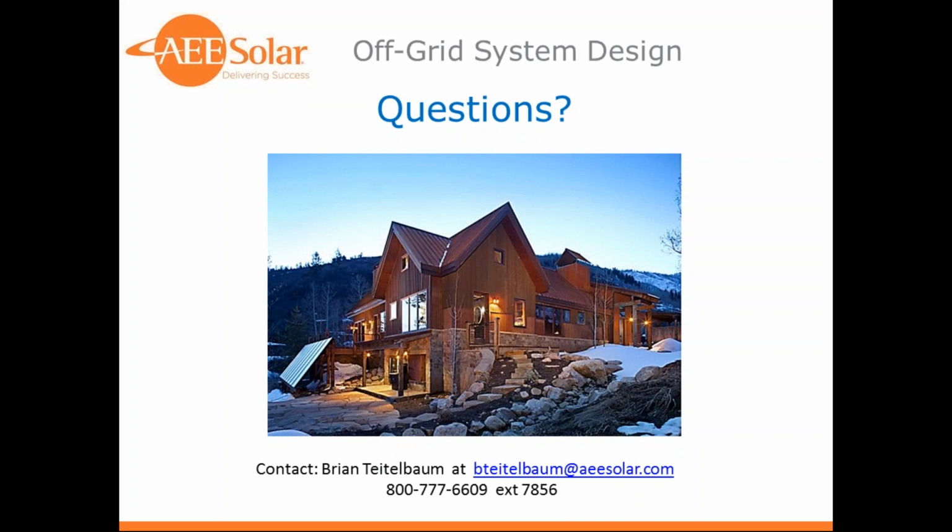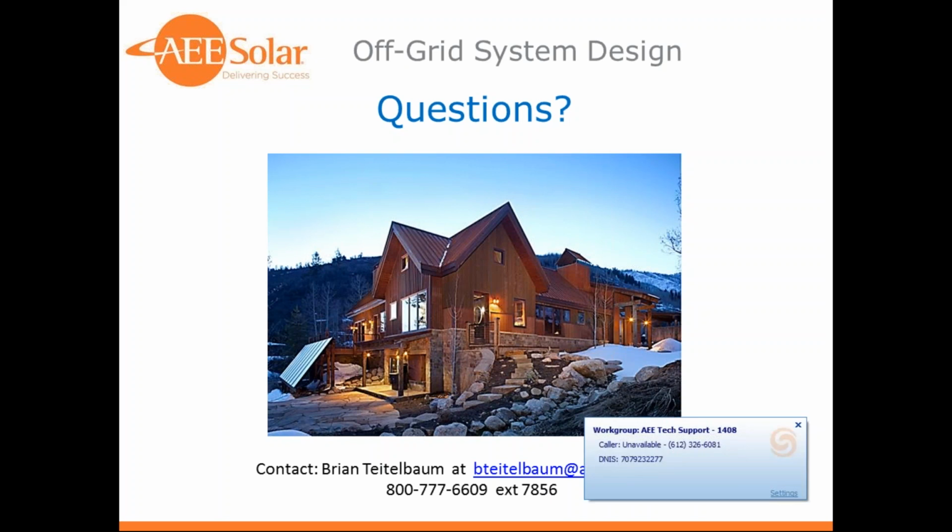Yes, actually most of the systems are not really based on percentage, they're based on battery voltage. The inverters these days have built-in what they call auxiliary relays that can be programmed for different voltage points. So when the battery voltage drops to a certain point, the generator starts. There are time delays built into these kinds of things too, because when you put big loads on batteries, the voltage drops. You don't want the generator kicking on every time the washing machine goes on, for instance. But there are relays that can do that.